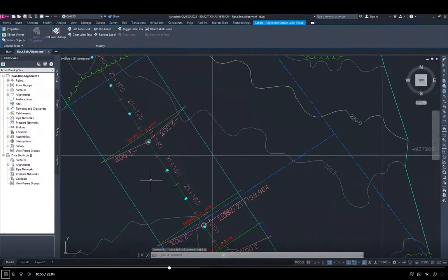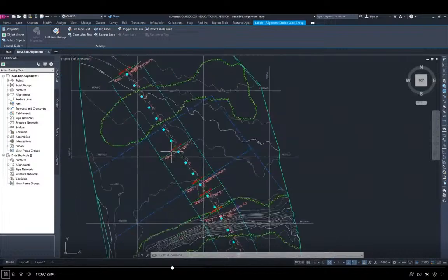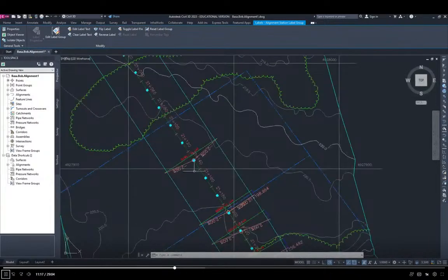And you can see now it's added to our diagram all the critical points where the super elevation occurs there. Basically, this is where the conditions A, B, C, and D that we speak about in class happen. Now, it looks like it's upside down, but remember, our road is coming from the top down this way. If you were to stand on the road at the beginning here and look down this way, then if you imagine this in a 3D perspective view, you'd be looking at these right side up, okay?